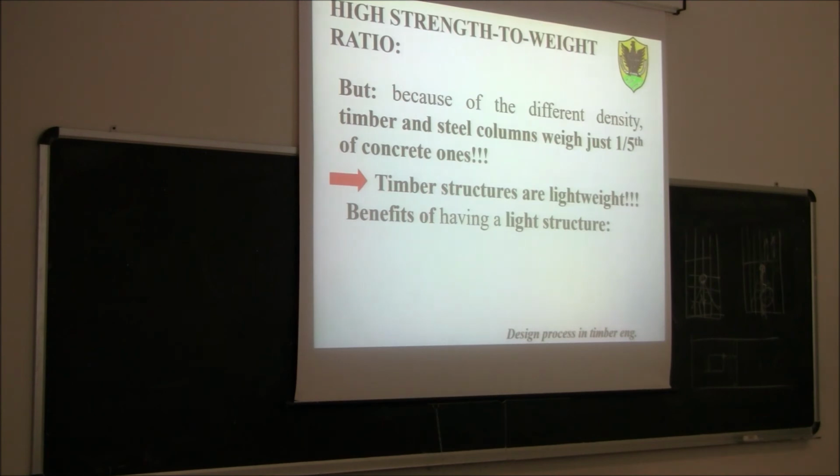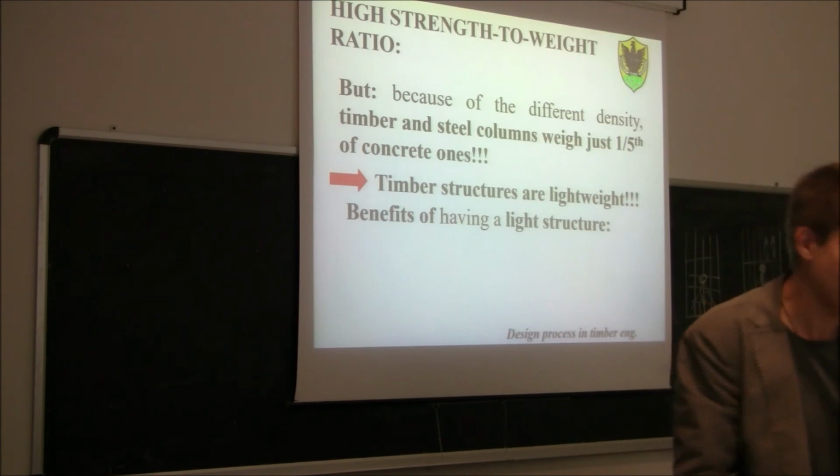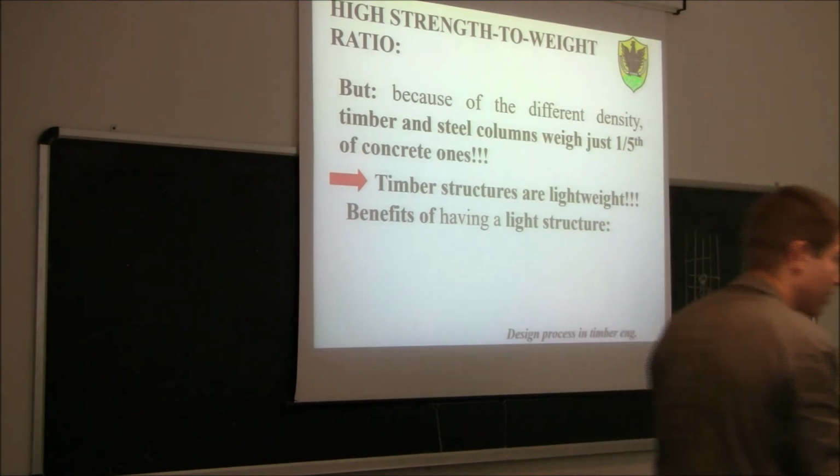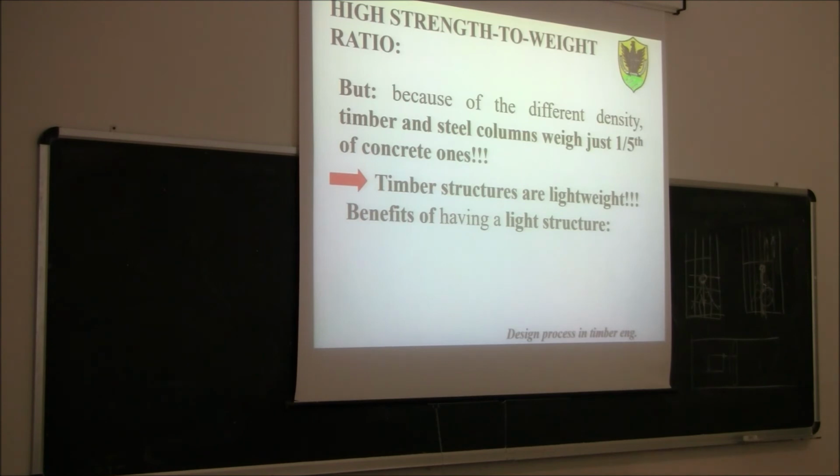Other advantages of a lightweight structure are related to the lower gravity load. But this lower gravity load must go down eventually to the foundation. So since I also have to design the foundation, I also have to check the ground which is underneath the foundation. Obviously, if I have a lightweight structure, the stresses in the foundation will be 5 times lower. Also the stresses in the ground will be 5 times lower. So you would say cheaper and easier foundation systems for a lightweight structure. Okay?